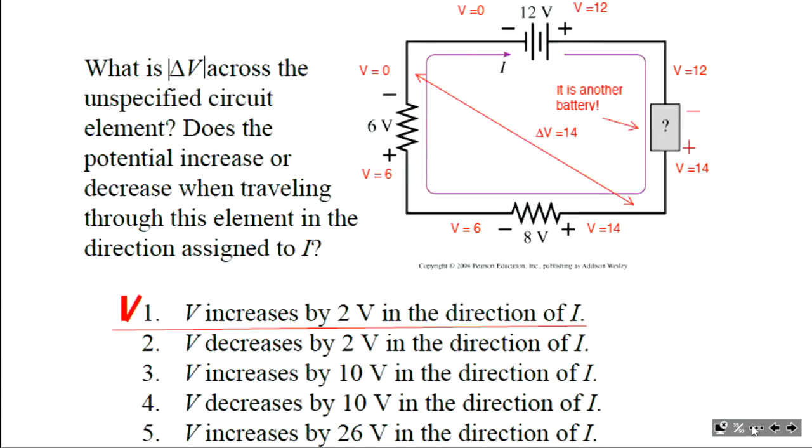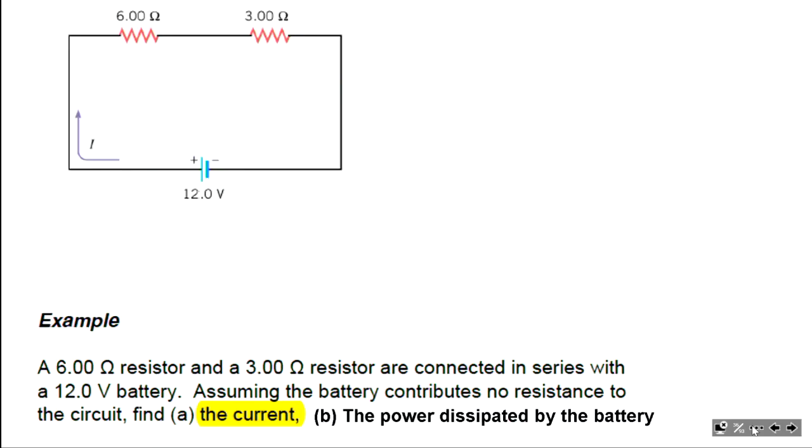Well, and very quickly, exactly the same reasoning tells us, so 0, 0 plus 6, 6, 6 plus 8, 14. This electric potential equals 14 volts, but that 12, how can it happen? That's not a passive element anymore. That's supposed to be a second battery. That's it.